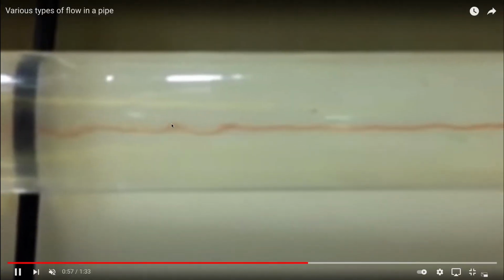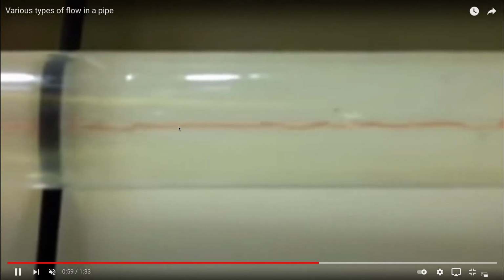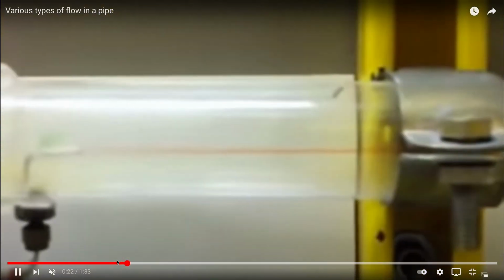And as you speed up the velocity within the pipe, you get these little vortices developing, and the manifestation of that in this case is being able to look at these squiggles in the dye tracer in the center. So presumably they're looking not only downstream, but also changing the velocity in this pipe to be able to get that. And it's getting a little more extreme as you go on. And so you can index with the Reynolds number.